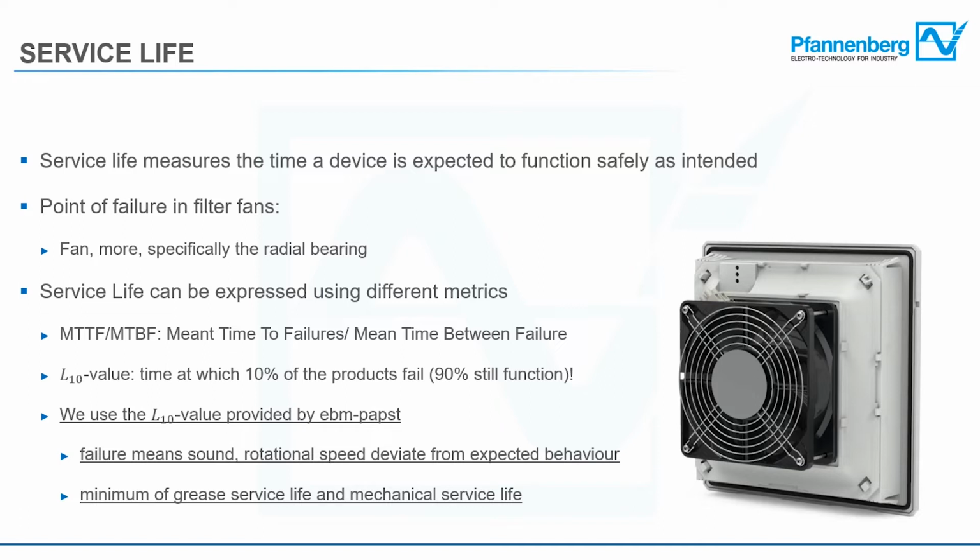At Pfannenberg, we use the L10 value provided by our fan provider EBM Papst. And in our case, failure means that the sound or the rotational speed of the fan deviates from the expected behavior, so it's not necessarily really broken in that sense. The L10 value we provide is the minimum between the grease service life and the mechanical service life, which I will get into in the following slide.